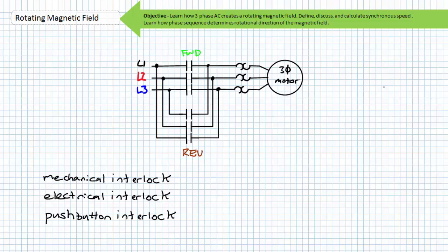Before we bring this lecture to a close, let me caution you that reversal of the 3-phase AC stator magnetic field must be performed with the utmost of care. On the power or primary side, motor reversal is accomplished using 2 3-pole contactors. One contactor is designated the forward contactor and respectively connects windings A, B, and C to L1, L2, and L3.